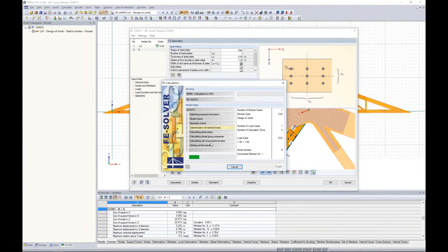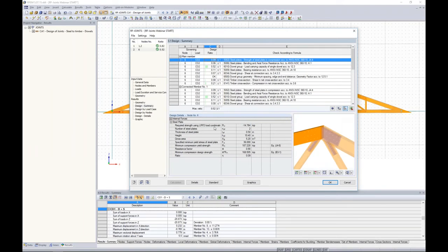Now we're ready to run a calculation. So again, solves rather quickly. You can see that this brace connection went over a little bit better than the last one. We have a controlling code check of 0.52 here. So everything looks great in terms of that.